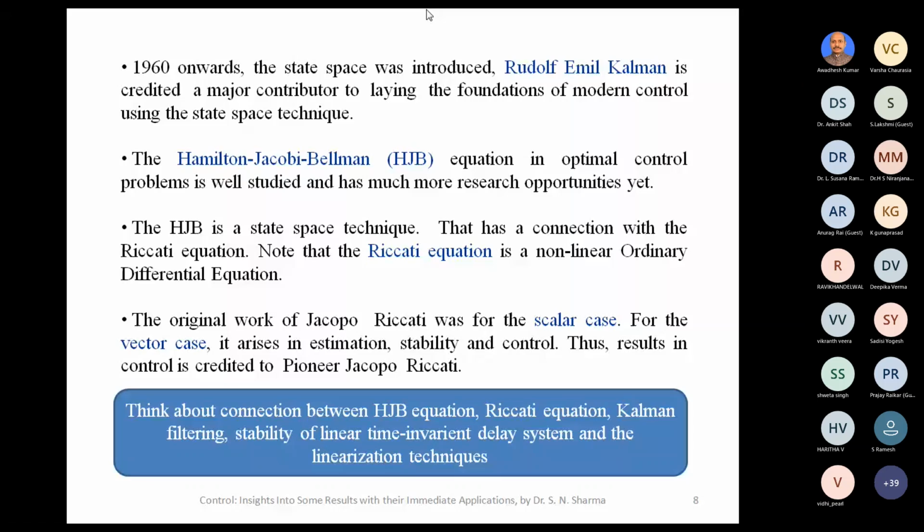You can prove the Riccati equation by adopting the Hamilton-Jacobi-Bellman equation for the deterministic case, with quadratic functions and positive definite symmetric matrices. Then you find that for any linear system, time varying or time invariant, you have to control it optimally, and then you have to use the Riccati equation.